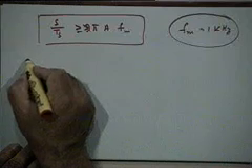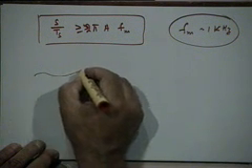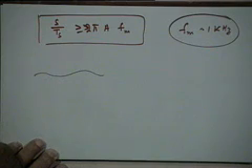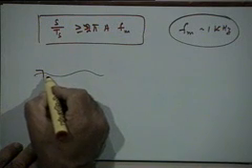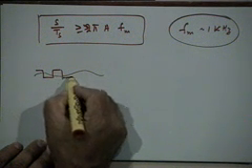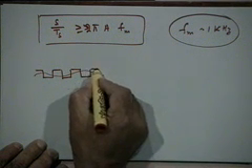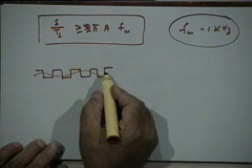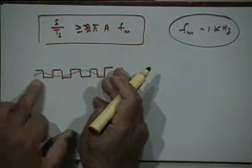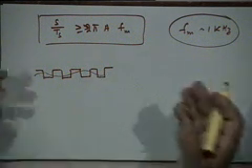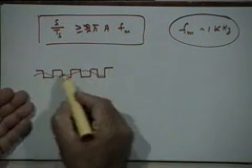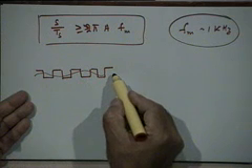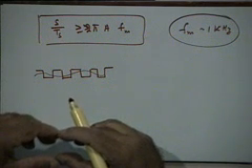The second one is, suppose your signal varies very slowly, or the amplitude of variations is very small as compared to the step size. Now let us see what will happen. The alternate steps will be positive and negative, isn't it? Now when you pass this through a low pass filter, what will you get? You will get a constant value. The average value of these positive and negative steps, which is what a low pass filter will produce, will be a constant value, and you will not be able to track these variations again. So very small amplitude variations also will get killed if your step size is too large.